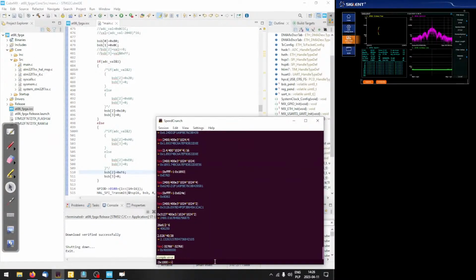Actually, we have to right shift it by 6, just because our phase word is 16 bits, but we use only the 10 most significant bits. So you have to discard the 6 least significant. So that gives us 64. And if we divide that by 1024, that gives us this. And this is actually not in degrees, but if we do something like this, yeah, 22.5 degrees.